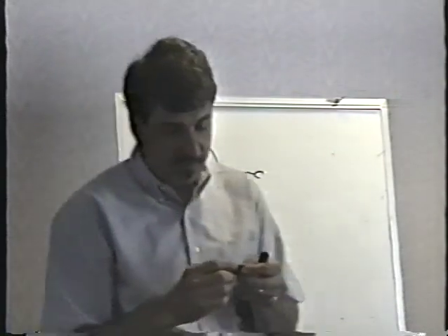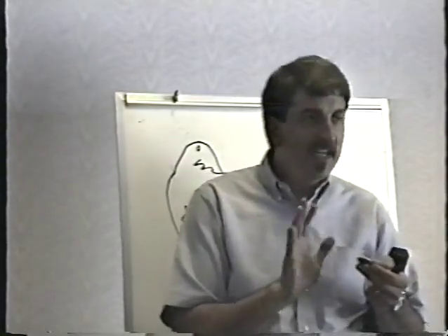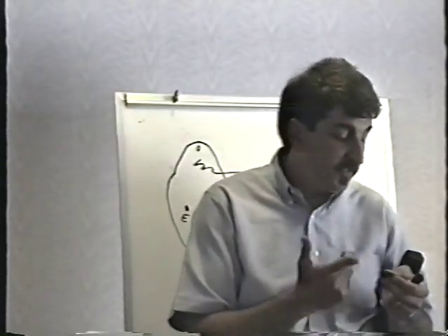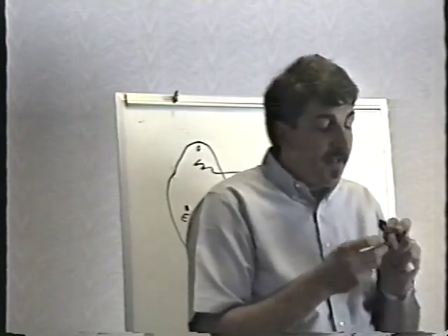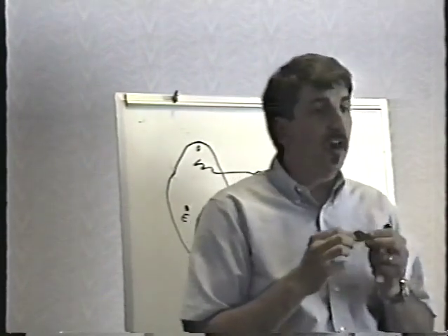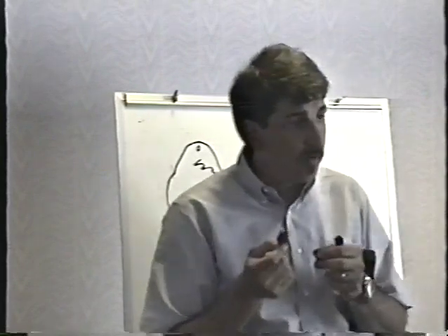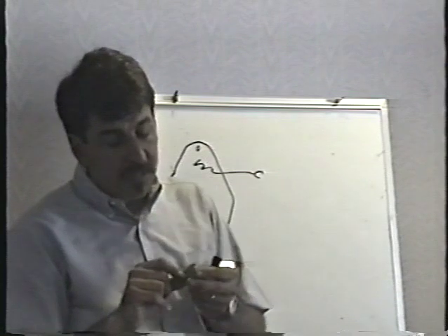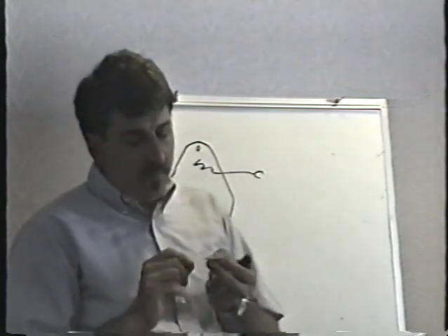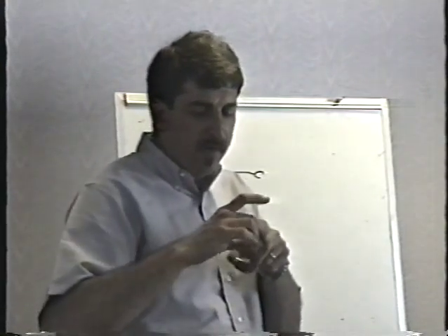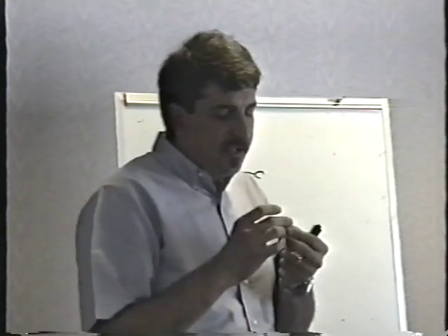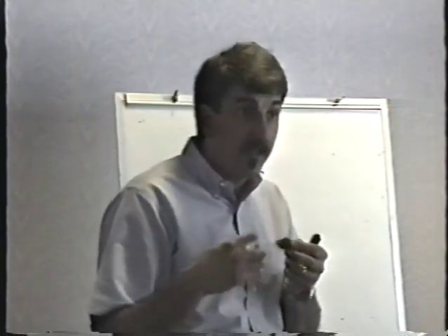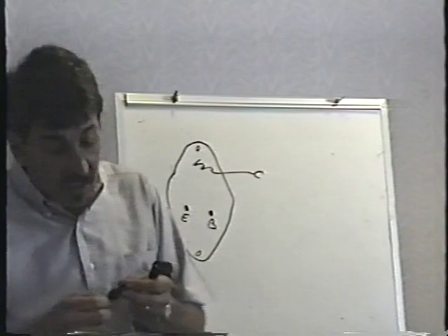It doesn't taste like toothpaste. So it is white goop. It did not come out of the transistor, although the transistor is filled with the same stuff. There's this stuff that they put on transistors called heat sink compound. You'll probably see it on Wednesday when we pull the power supplies apart. This heat sink compound is put on the back of the transistor and also on the heat sink, on the insulator and on the heat sink. It's used to help conduct the heat away from the transistor. It's not electrically conductive, just heat conductive, thermally conductive.